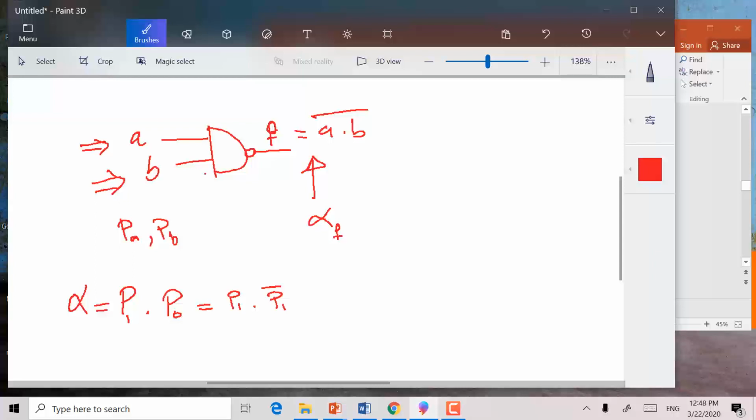Keep in mind, we understand that some signals take more than one state, like 0, 1, or high impedance. We are not discussing those yet. We're going to limit ourselves to signals with binary values of 0 or 1. So the probability of a signal being 0 equals the inversion of the probability of 1, which is equal to 1 minus the probability of 1.